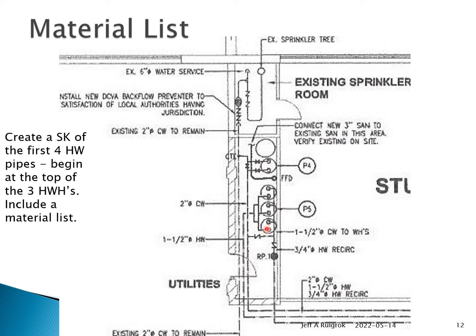And what that means is every pipe that comes off the water heater is the exact same size. So these pipes that run to the left are the exact same size. These 2 pipes here and here are the exact same size. And even these little legs on opposite corners here are the same size. And you do that so that every water heater sees the same amount of water flow through it. It's called equal draw, equal feed. Anyways, just to do a real rough sketch for you, I'll do the hot water piping, which is this one. So remember, these pipes are all the same size.